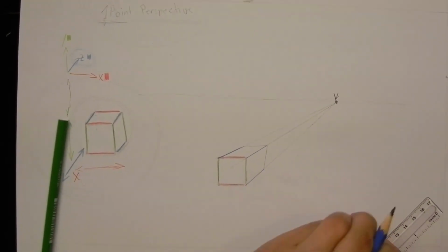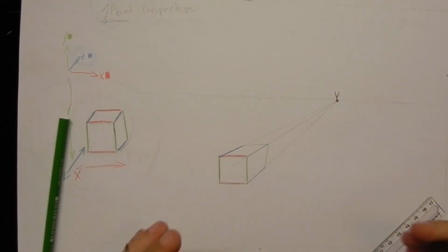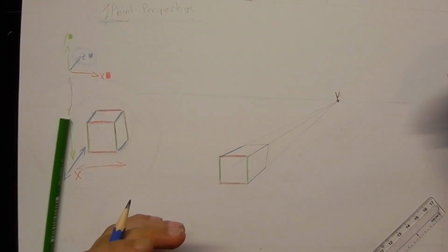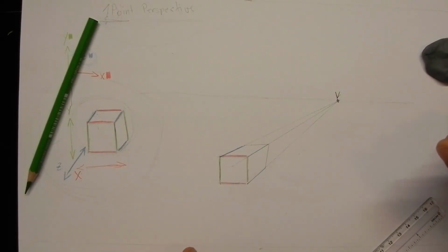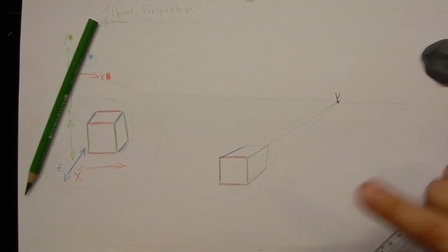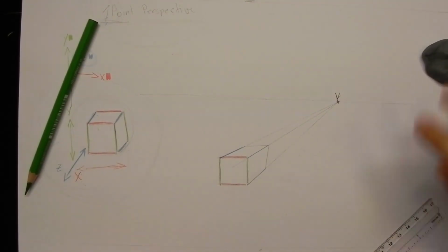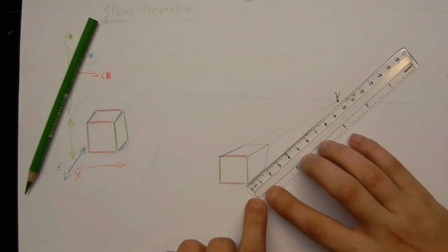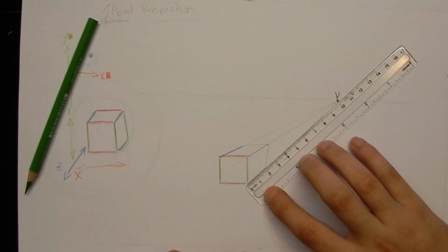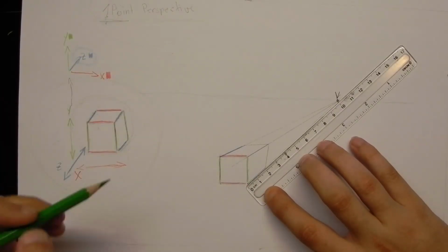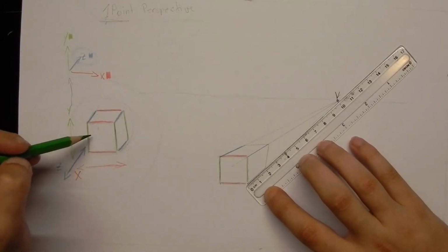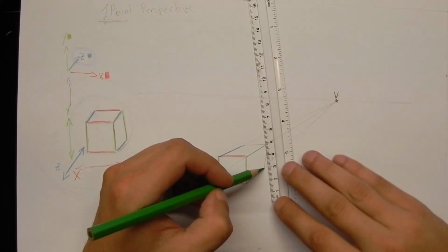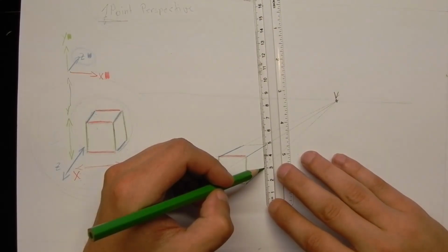You can't do usual measurements on axes which are affected by the perspective system, but you can rely on those which are not affected. Which means I just take any 2 centimeters, like this Z line, and as we know the Y lines are parallel to each other, I take this point and just draw a parallel line upwards.